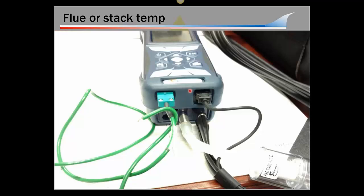And that's all good and fine if you're doing readings on furnaces that are pulling their combustion air from the same room the furnace is in. Okay, water heaters, 80% furnaces. But when I get into high efficient furnaces that have two pipes, one pipe being the flue or the exhaust and the other one being the intake, if I'm standing in the house and the house is 68 degrees, but the outdoor air is 0, there's a large temperature difference there, is there not? And this probe needs to be used, and this guy inserted into the combustion air pipe.